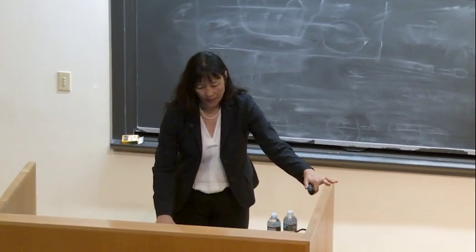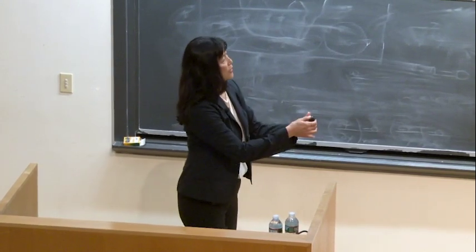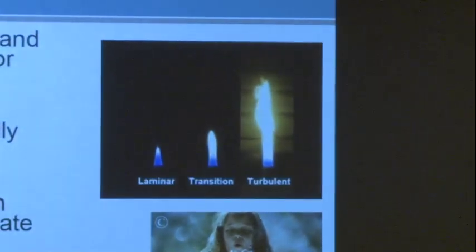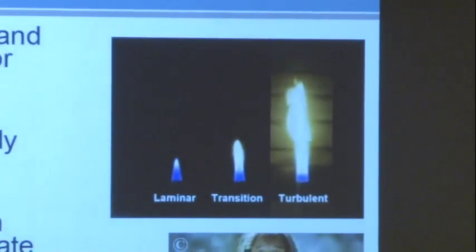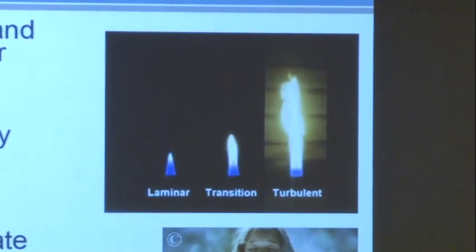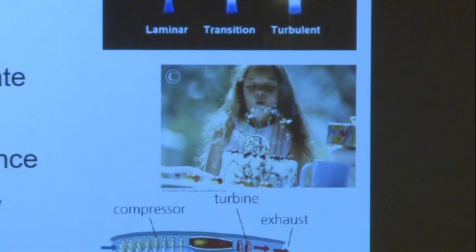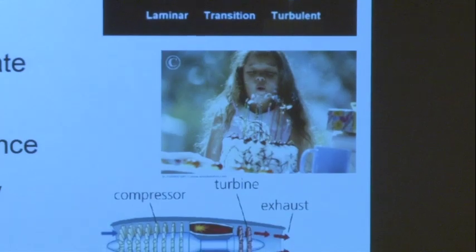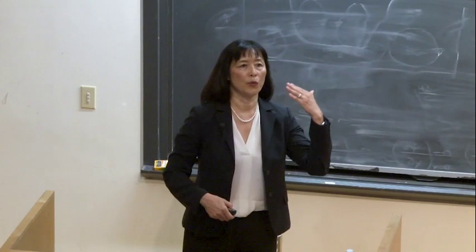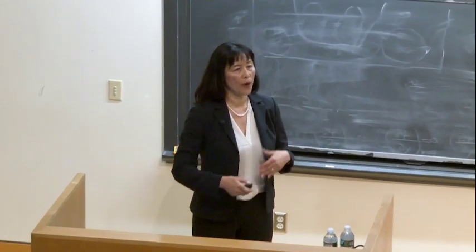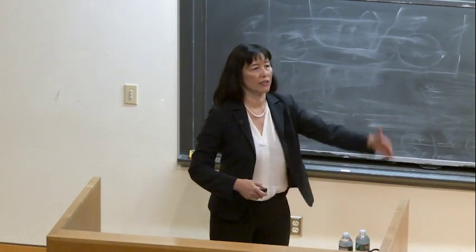Okay, and the simplest example of that is shown in these pictures where, we've all had birthday candles where if you blow a little bit, it seems to burn more intensely, and if you blow too hard, it goes out. And non-premixed flames are notorious for having extinction limits, where if you go beyond that, you're gonna put out the flame. Premixed flames often are more robust, especially when you have large recirculation zones of hot product gases surrounding these flames that always supply heat and temperature to the flame.